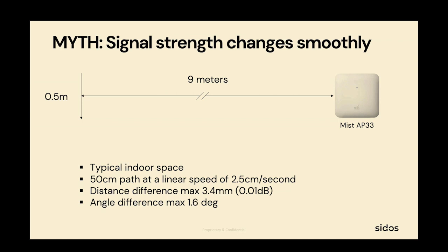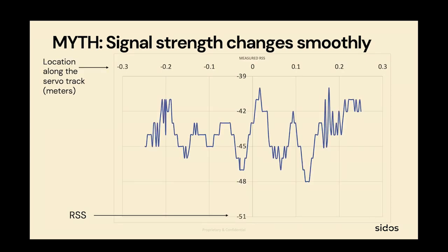So in a perfect world, all RSSI readings should be the same, right? Same TX power, same distance, same angle, same RSSI, yeah? Well, RF is weird, so this is what I measured. On the top, you see the displacement from the center point, so half a meter, and this is the RSSI changes. There's a spot somewhere around here, where within 10 centimeters, I can record anywhere from -48 to -40. And because this is constructive and destructive multipath, it's not time variant.